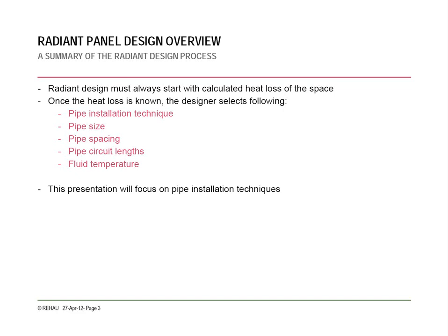So once the heat loss is known, the designer can go through and select the installation technique and then the pipe sizing on all the associated pieces, the pipe ends and fasteners and whatnot. So in this presentation, we're going to focus on the actual installation techniques, and then I'll touch on the others later.